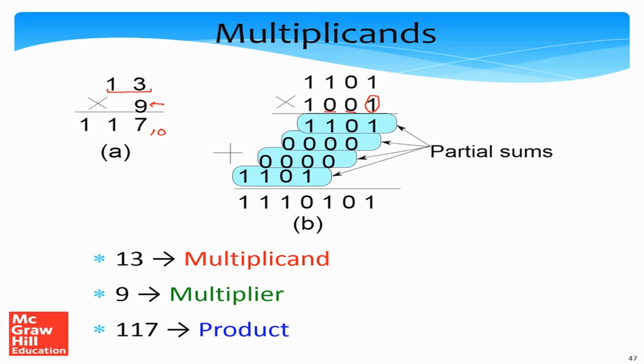Next, in the next digit, we again have a 0, so we write 4 zeros once again: 0, 0, 0 and 0. And finally, we come to the leftmost digit, or the MSB digit. Since we are looking at unsigned numbers, we are relatively safe for now, and this is not the sign bit. So we multiply again 1101 times 1, where the result of that multiplication is 1101.